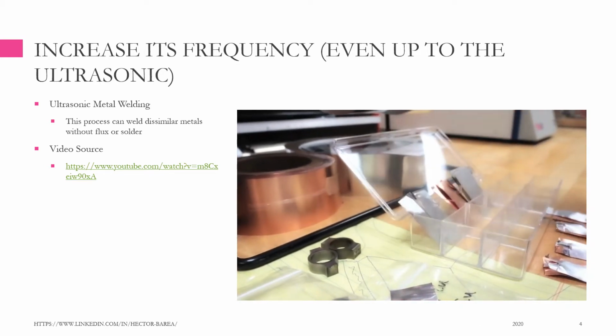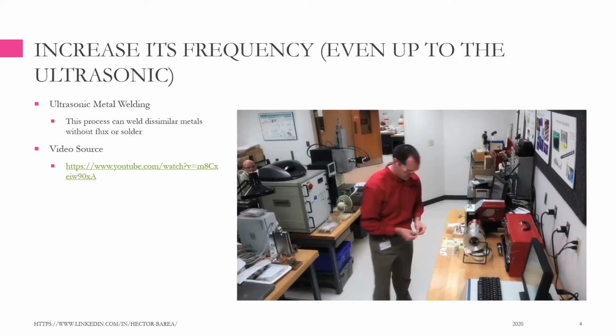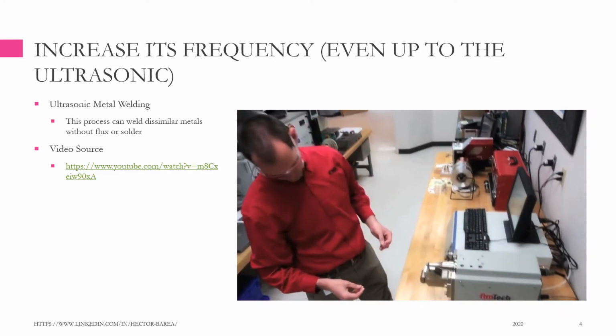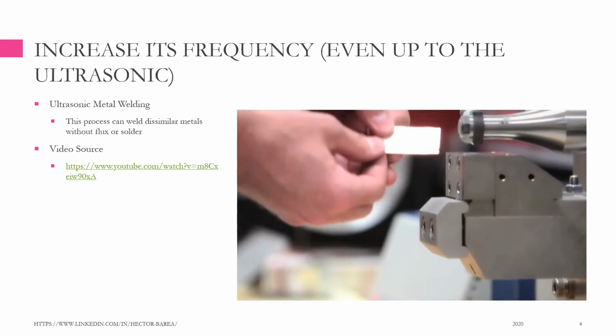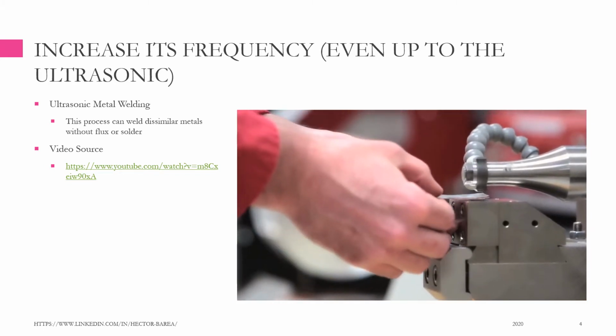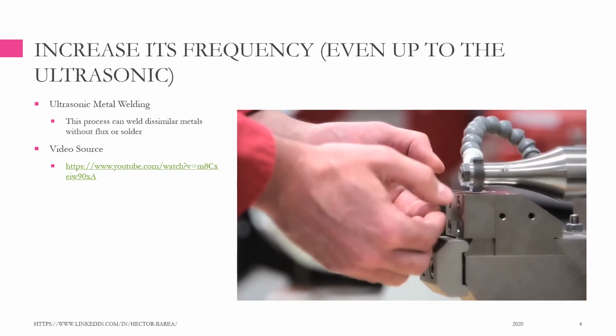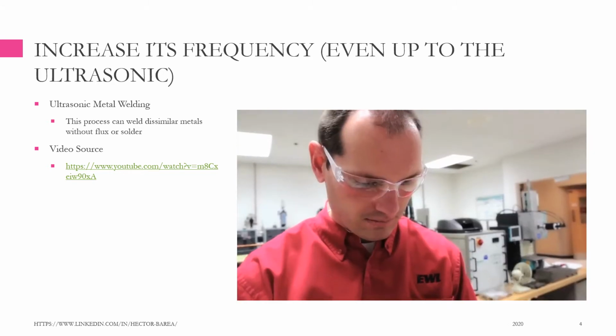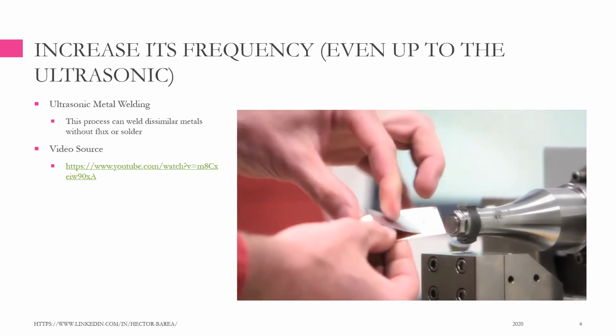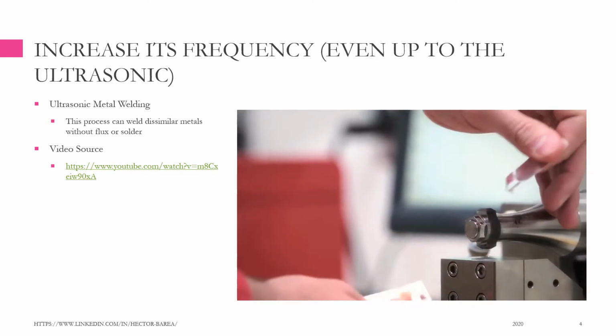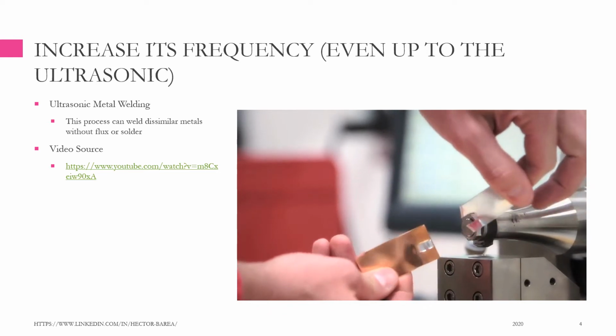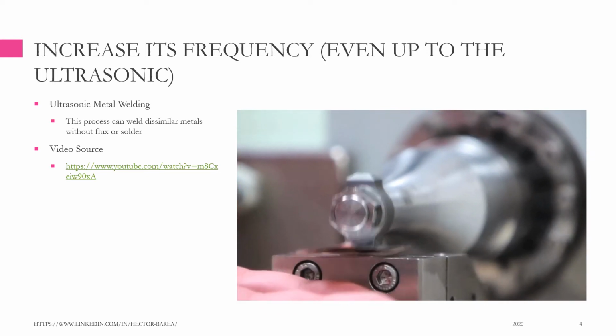Ultrasonic metal welding can be used to efficiently join similar or dissimilar material combinations. Because this is a solid-state process, materials only reach 1/2 to 1/3 of their melting point. This avoids issues associated with a mismatched coefficient of thermal expansion between two dissimilar materials, which leads to joint failures.